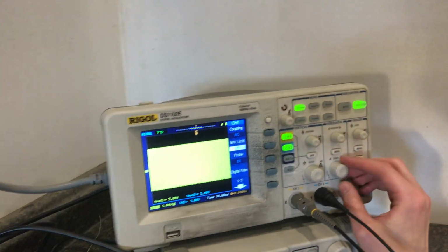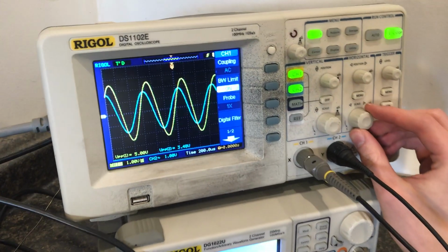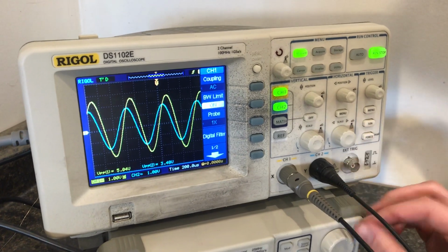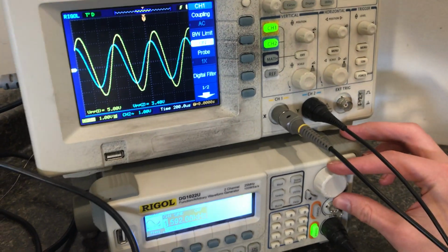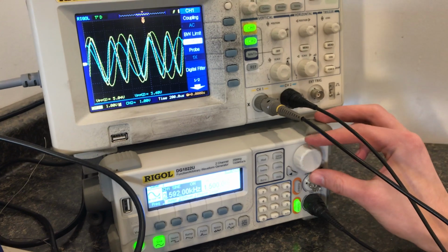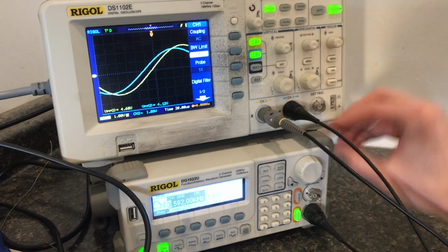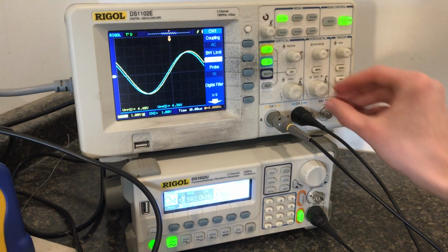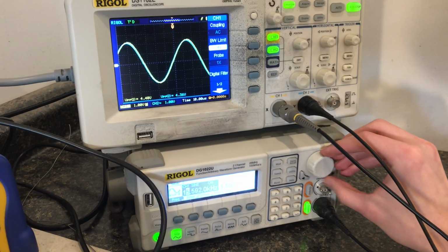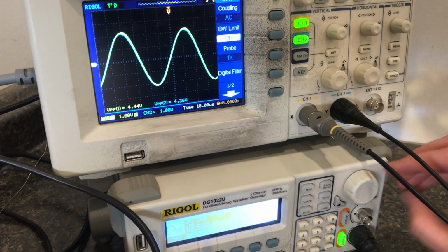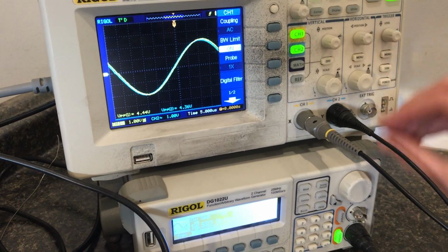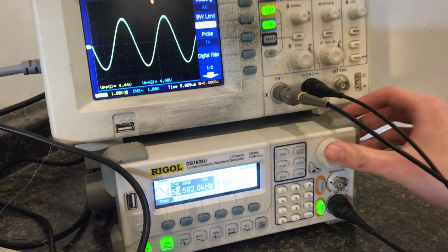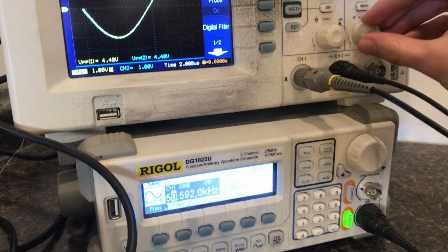Okay, so it looks the same at the corner frequency for both circuits, but the difference is, as I increase the frequency here, since it's a high pass, the output is approaching the input. By the time I get to about 10 kilohertz, it's becoming hard to tell. Let's put this at about 50 kilohertz. I mean, they're right on top of each other.